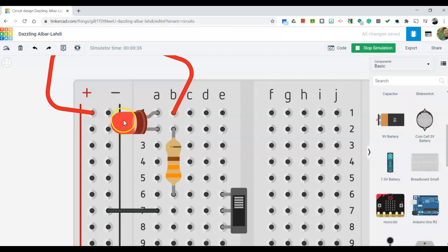Then the electrons come through the cathode, through the terminal of the resistor in this direction, and out the terminal and through the breadboard rail, this rail right here, through the switch. Since the switch is closed, there's a connection right here that's bridging the gap, and the electrons are coming in this direction and out to common and back through to negative.